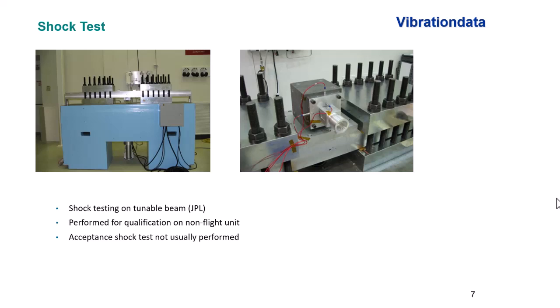I've got a note here that shock testing of this sort is normally done only as qualification. We don't want to do an acceptance shock test on flight components because of the potential for inducing damage, and we just don't want to go there.